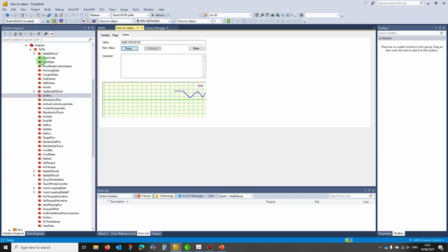As I'm moving the encoder, you can see that encoder position is coming through, and that shows that if you had something to absorb that encoder reference, like MC gear in, MC cam in, or our EGB interface, that would be enough to drive it and to give it a position reference.